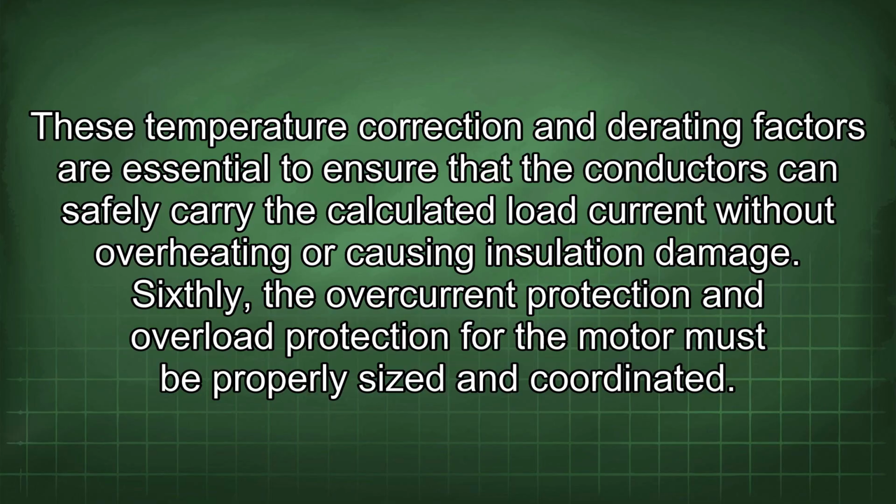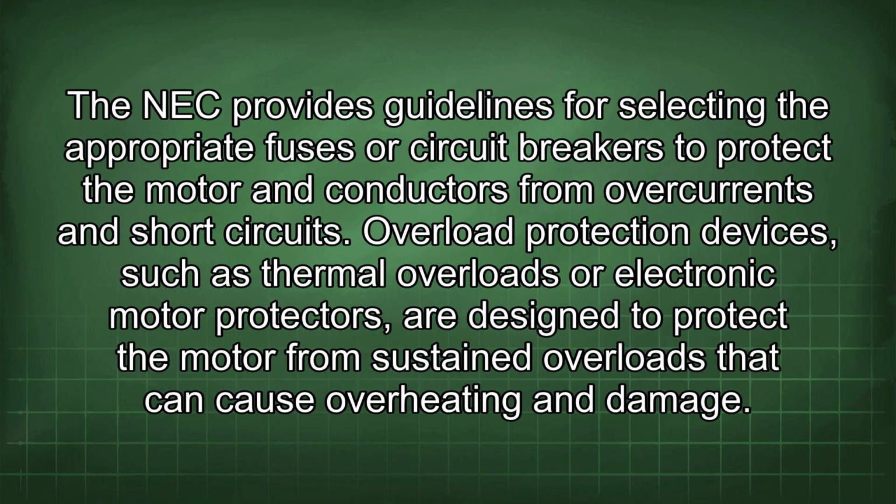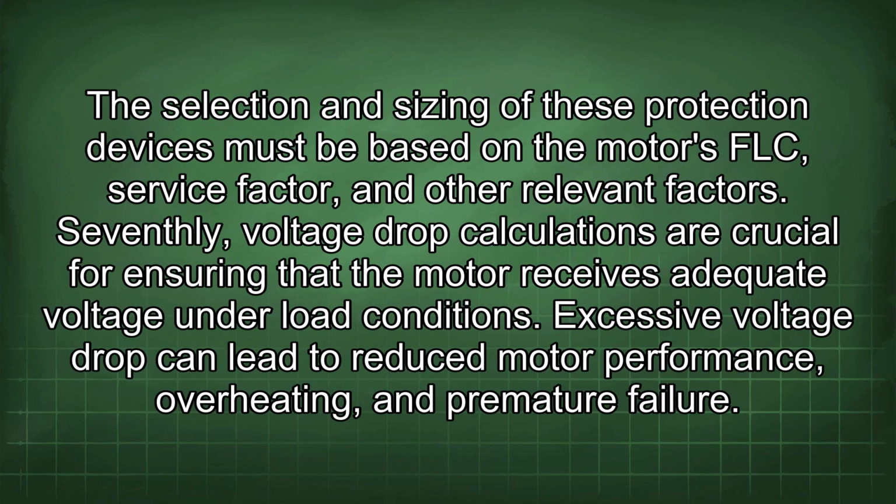Sixthly, the overcurrent protection and overload protection for the motor must be properly sized and coordinated. The NEC provides guidelines for selecting the appropriate fuses or circuit breakers to protect the motor and conductors from overcurrents and short circuits. Overload protection devices, such as thermal overloads or electronic motor protectors, are designed to protect the motor from sustained overloads that can cause overheating and damage. The selection and sizing of these protection devices must be based on the motor's FLC, service factor, and other relevant factors.